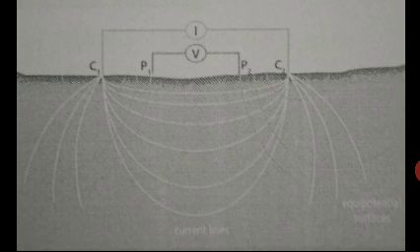Whereas electrical sounding is done to determine vertical changes in resistivity, which reveals the change in lithology at a particular place with increasing depth. In profiling or sounding, there is scope for electrode arrangements to be made in different ways in the field, and such arrangements are called electrode configurations. The two main configurations commonly used are the Wenner configuration and the Schlumberger configuration.